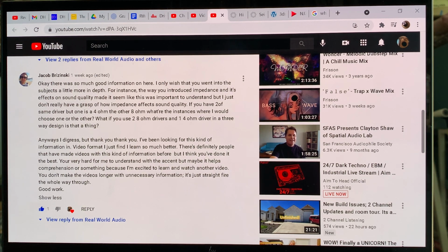driver. So if you want to do some loudspeaker design, first single driver speakers, then a very simple crossover with a simple two-way design, and after you have had about, I would say, a decade of experience with these, only then I would recommend that you tackle a three-way design, because making crossovers for three-way designs is a task for master speaker builders, and with the material that I have shared with you, we are really far away from that level yet.